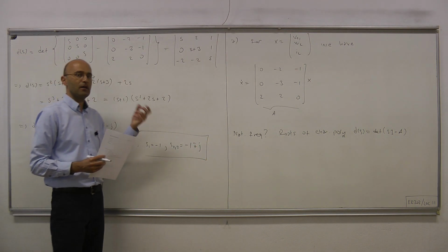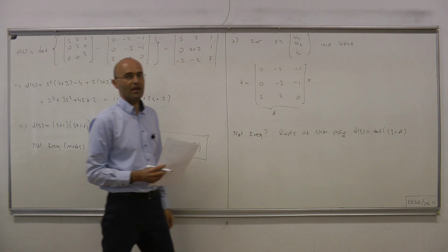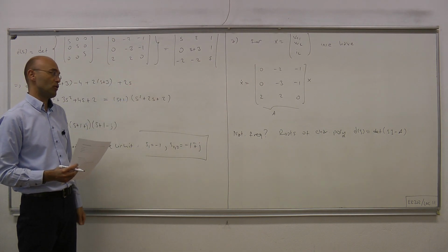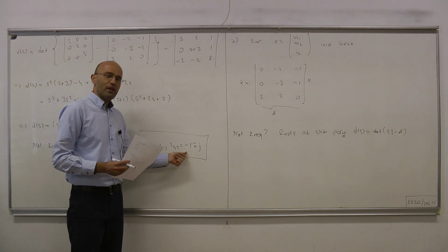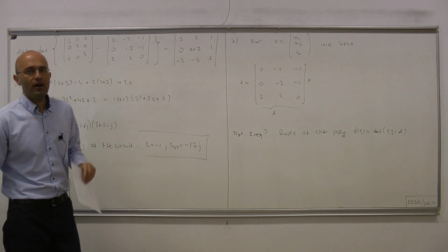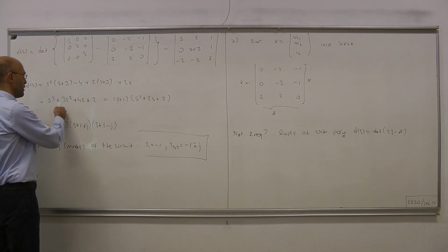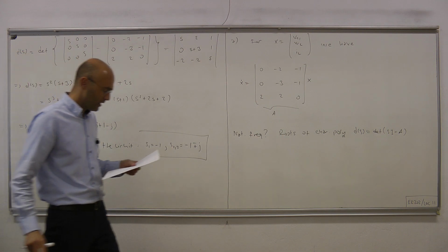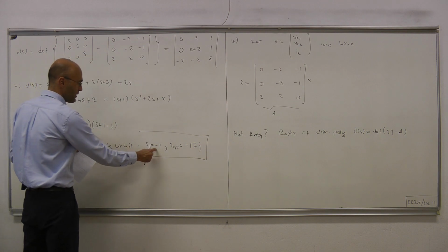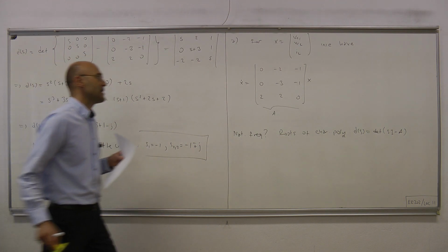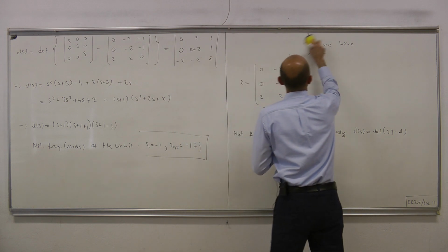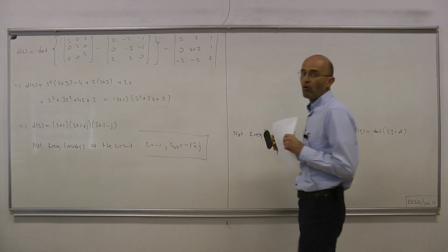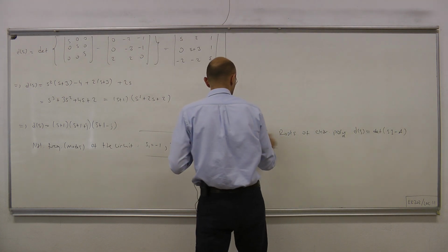Note that since we're dealing with real valued A matrices, which will always be the case because we're dealing with a real circuit, whenever we have a complex root, its conjugate must also be one of our natural frequencies because the coefficients of the characteristic polynomial will always be real. Okay, now having obtained the eigenvalues of the A matrix, we can reach some conclusions regarding the general form of the natural response.